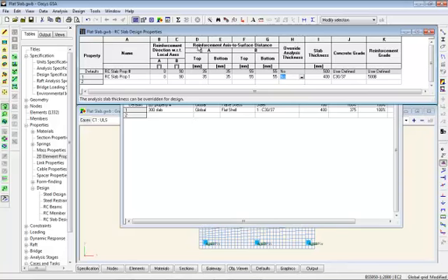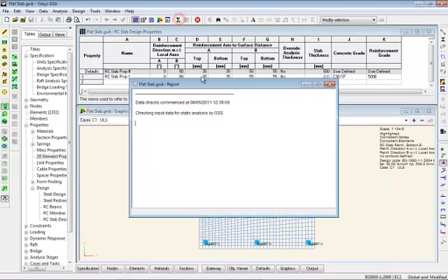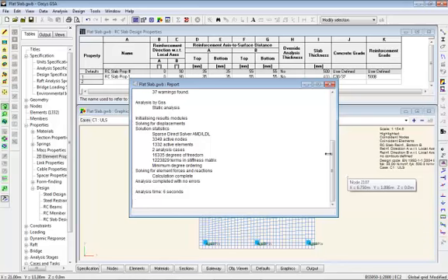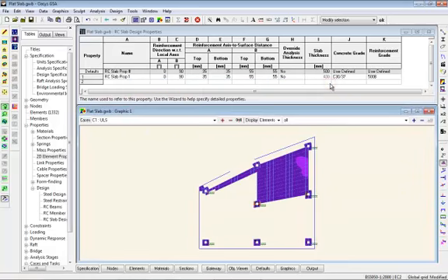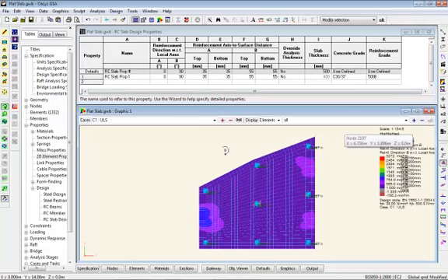For the final checks, obviously this will affect the self-weight calculations. So let's just recalculate that. So it does the analysis, and you see it's doing the design. And okay, you see it's increased self-weight, so it hasn't increased the bars. So it's a little bit iterative, this.